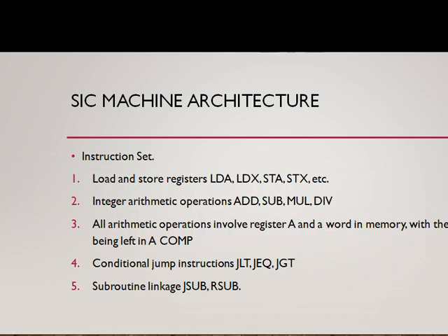Next one, instruction set. We have 5 types of instruction set here. First one, load and store register. The load and store register instructions will load the register and store the register. LDA, LDX, STA, STX. LDA and LDX perform the load register operation. STA and STX refer to the store register operation.